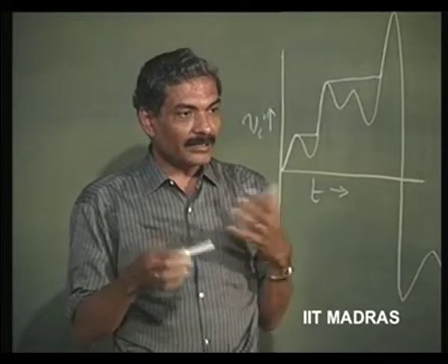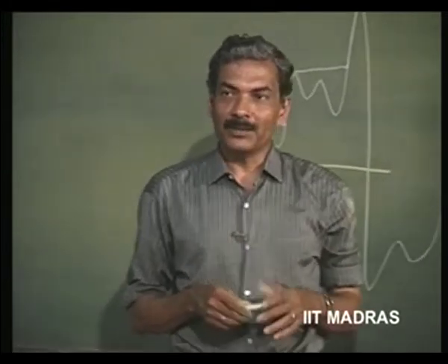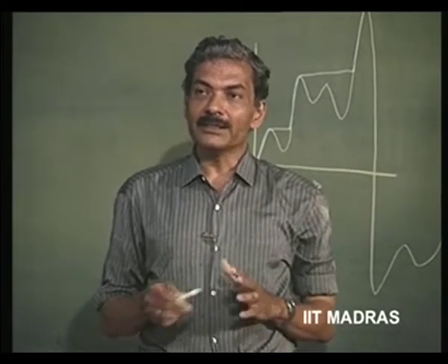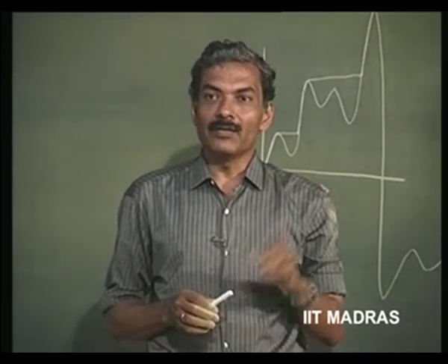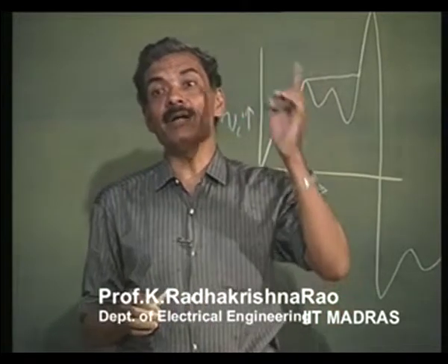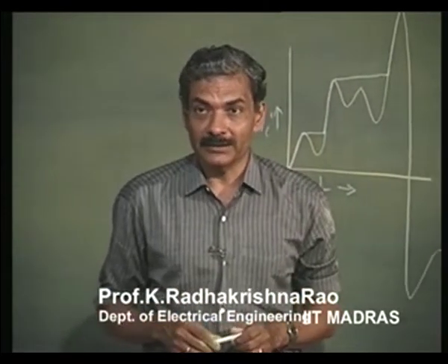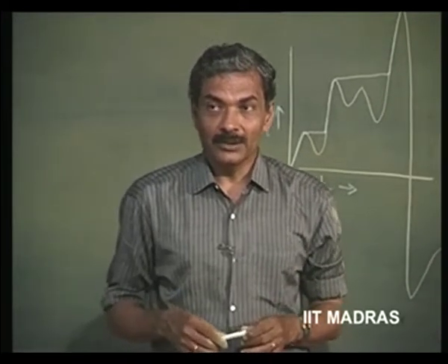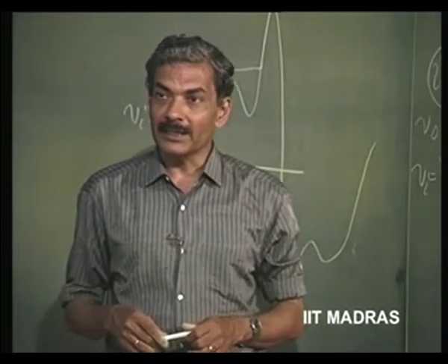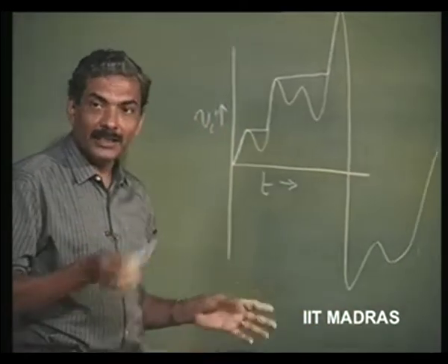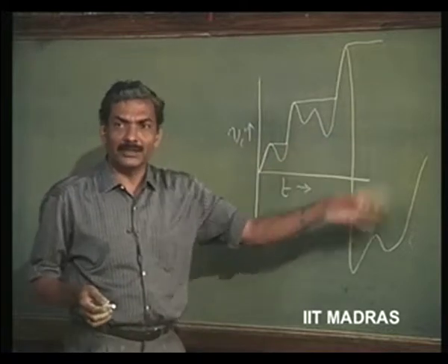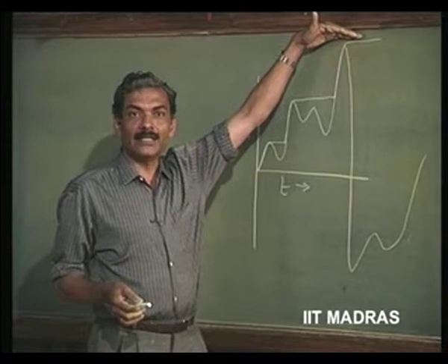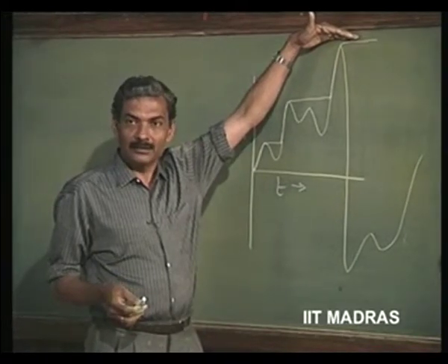Let us say a temperature of a particular furnace is to be monitored, and I am not interested in the intermediate values. I would like to know what is the maximum ever value reached by the furnace, under what circumstances, at what time. So if you just put the peak detector like this, it will keep on monitoring the temperature, the waveform will be keeping on fluctuating, right, but the peak detector will always indicate the highest temperature ever recorded in the time interval.